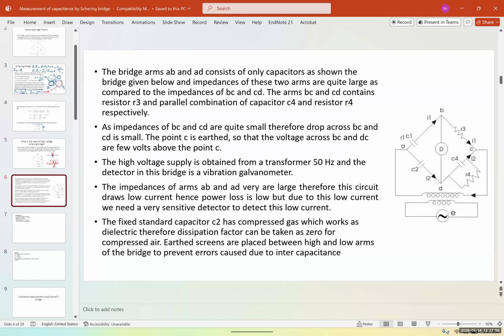So another problem that these have, and we have this in a lot of transistors as well. In high frequency, when you have an element like a resistor or transistor, you have the terminals coming out of it. These are two conductors. You have air between them, and they act like a capacitor as well. And this is actually very low capacitance. When the frequency goes high enough, this resistor or transistor actually becomes short-circuited because you have a small capacitor, and that acts like a high-pass filter.